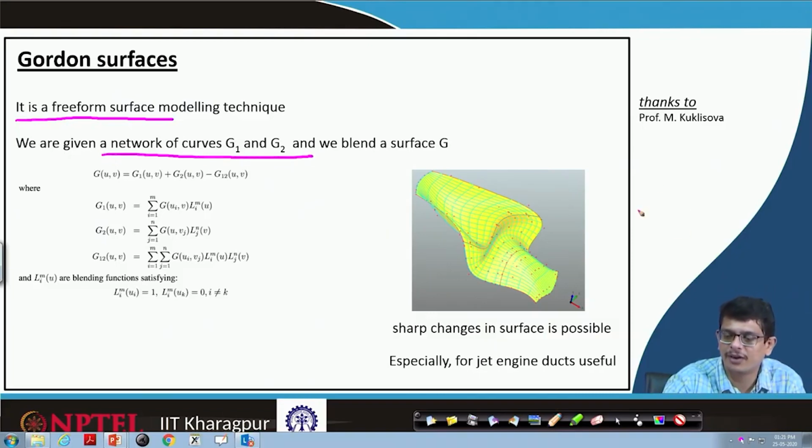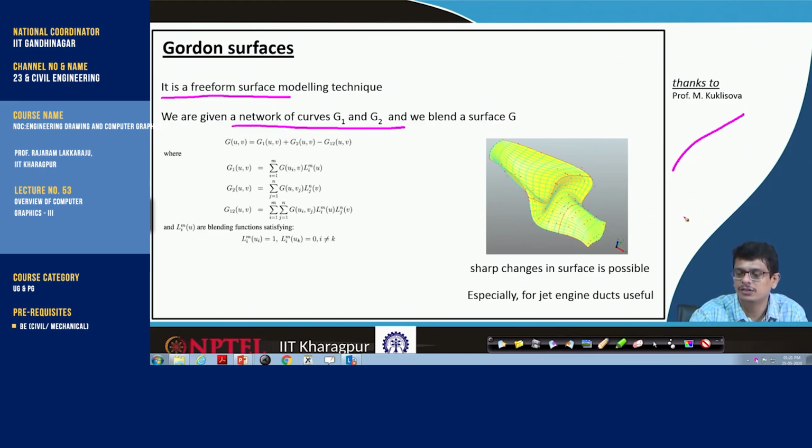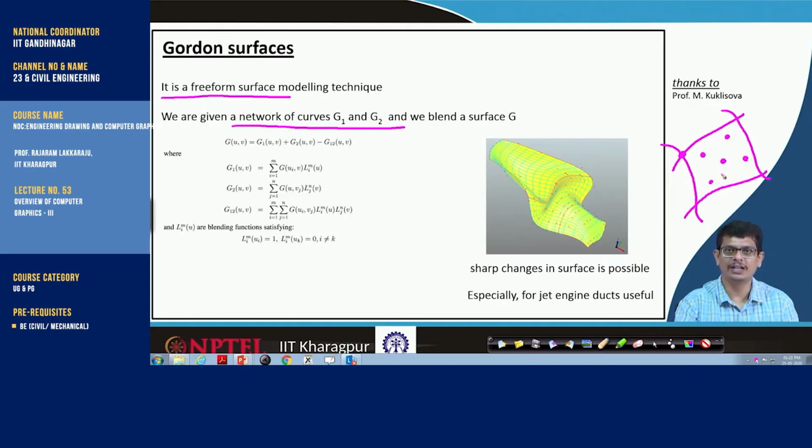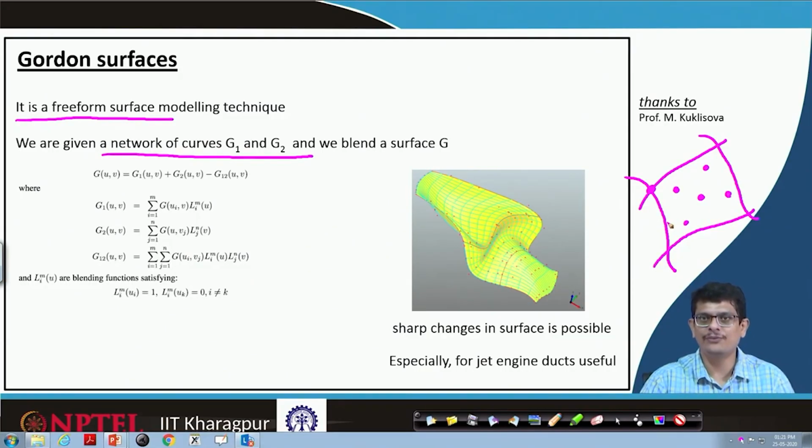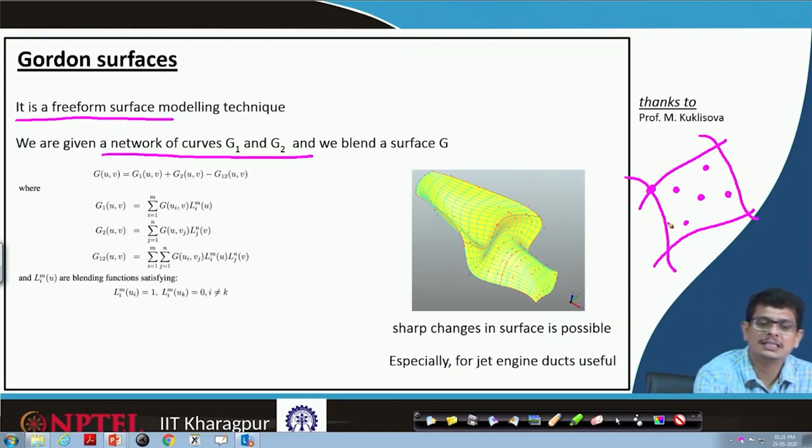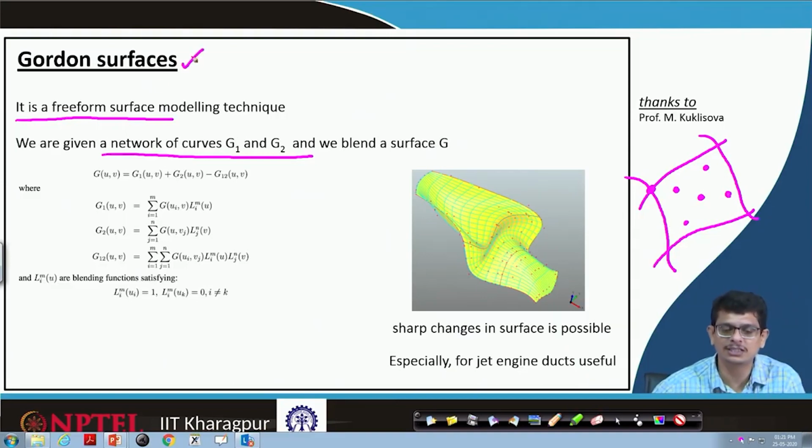For example, this is one curve, you have another curve, and another curve, and you have isolated data points here and there. Now, using your CAD software, you can pick one of the data points and move your mouse here and there, so that you start seeing the surface variations. And you carefully pull your surface at all these points, nicely mapped to get a smooth kind of surface. That kind of surface is what we call Gordon surfaces.